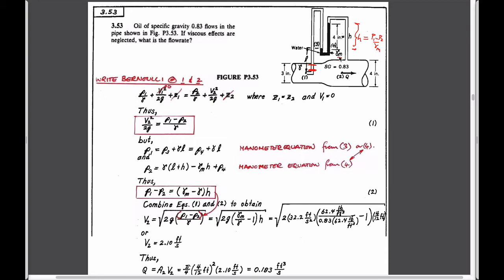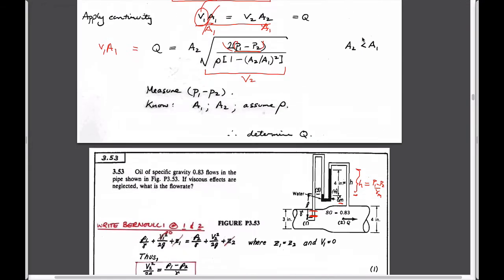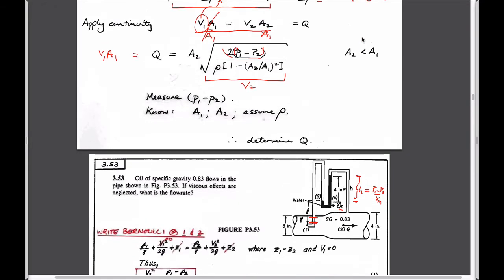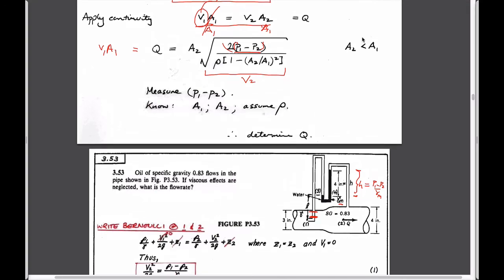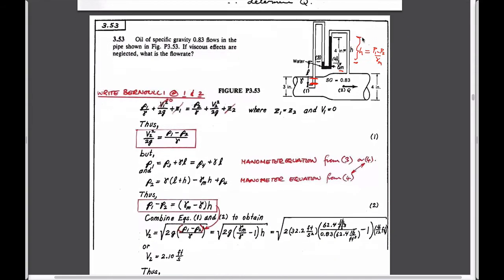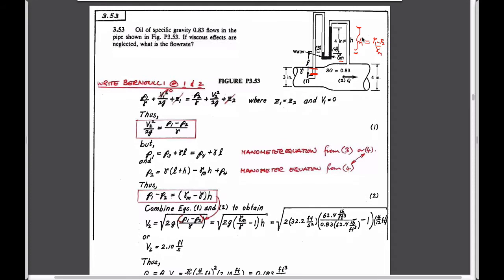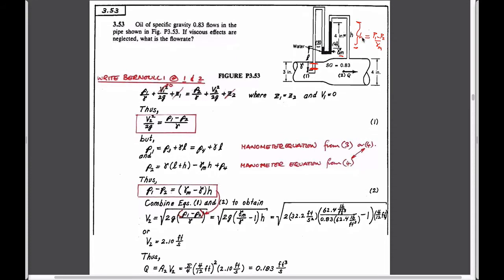Or you could do it differently, keeping this intact and having this pointed upstream. But the principle is the same in terms of being able to use it. If you had these tubes not pointing upstream, so that you were not destroying velocity, you could go ahead and just directly use this expression here, and you could put it into here, and you'd end up with the appropriate flow rate across the system, taking into account the ones and the twos, of course, the upstreams and the downstreams.